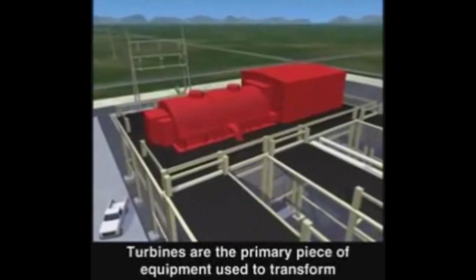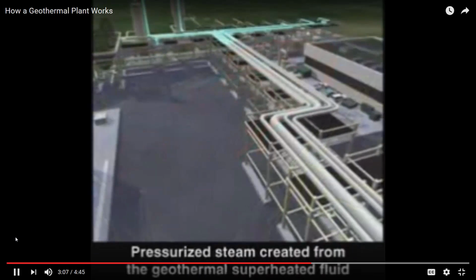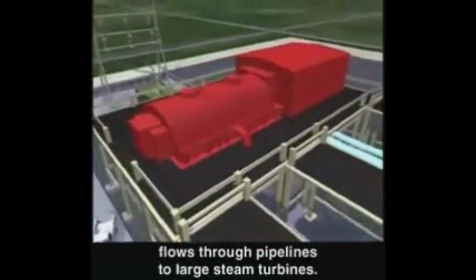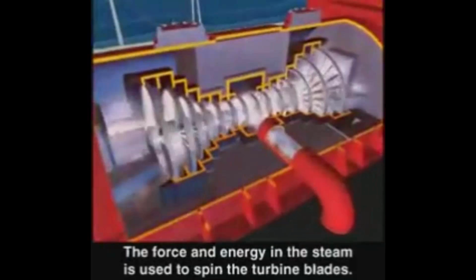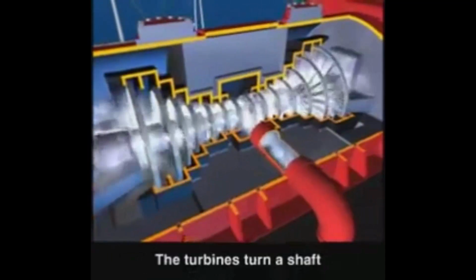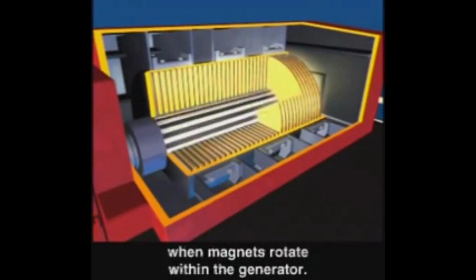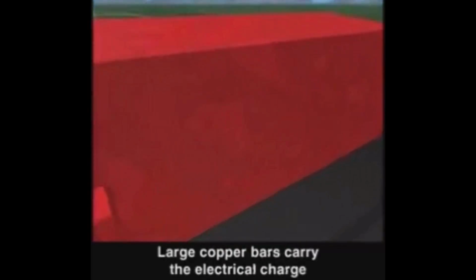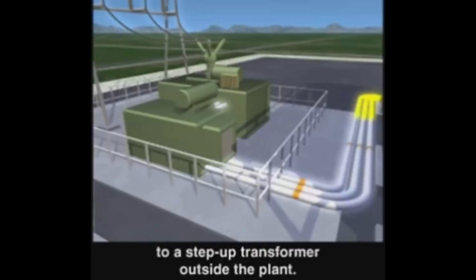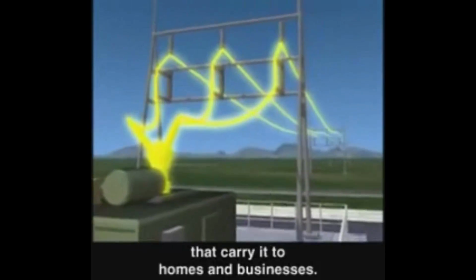Turbines are the primary piece of equipment used to transform geothermal energy into mechanical energy. Pressurized steam created from the geothermal superheated fluid flows through pipelines to large steam turbines. The force and energy in the steam is used to spin the turbine blades. The turbines turn a shaft directly connected to an electrical generator. An electrical charge is created when magnets rotate within the generator. Large copper bars carry the electrical charge to a step-up transformer outside the plant. Within the transformer, the voltage is increased before the power is sent to the power lines that carry it to homes and businesses.